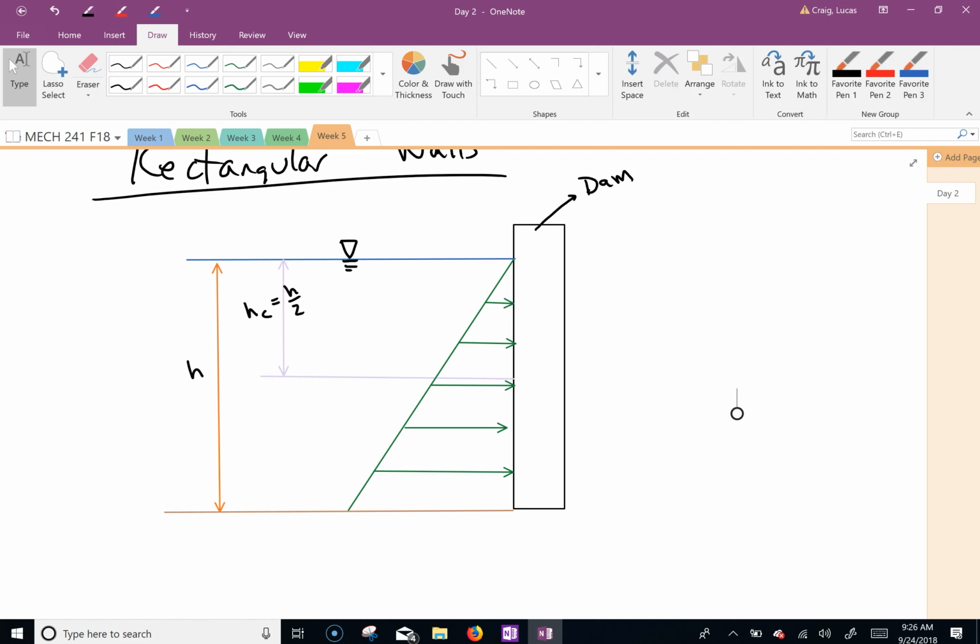Over here, now we add water. You still have atmospheric pressure on this side, right? Because you have to include it in this pressure term. But what about the right side? What's acting on this side? Atmospheric pressure too. So they cancel. So you don't have to worry about that. That's again why we kind of go with 0 anyways, because it makes life easier. So you never have to worry about adding atmosphere on here because they're on both sides. Does that make sense? Okay.